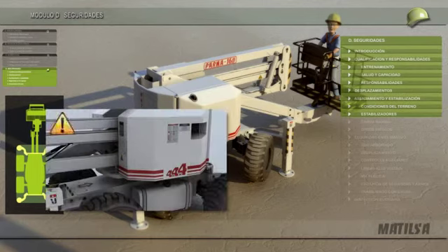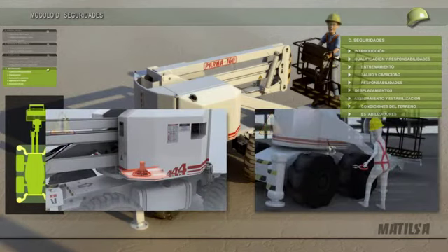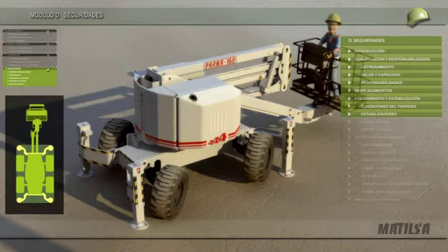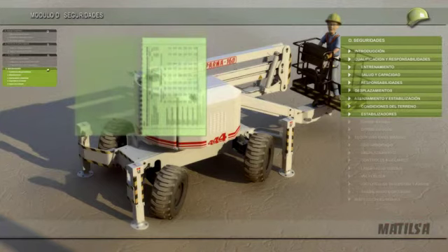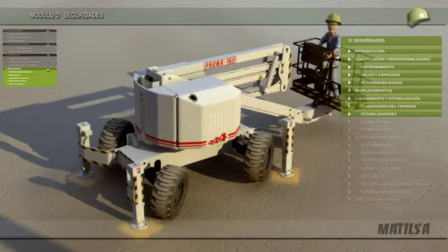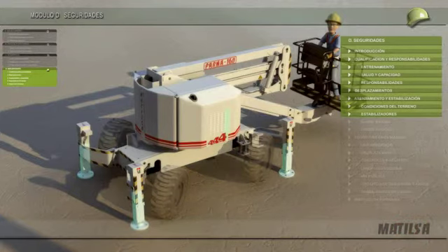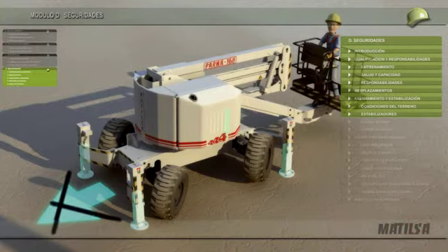If they do not have them, failure of the tilting device or negligence on the part of the worker when bypassing the signal will enable them to raise the basket without its being properly stabilized, and this may cause serious falls. Before elevating the platform, you should make sure that the stabilizers are creating a force against the floor and over the surface with the correct resistance. We will stabilize the platform within the limits that the manufacturer stipulates. If necessary, we will put some appropriate boards under the machine to increase the surface contact of the stabilizer with the ground. When using stabilizers, the weight should press down on the stabilizers and not on the wheels. You should never move onto another place of work with the stabilizer out and extended.